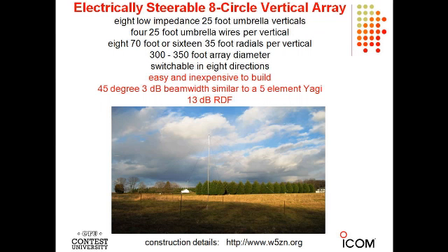At the base of this antenna, these low impedance antennas work best when they are tuned to resonance. They work well even if they're not tuned to resonance, but they work best when they are. And all that's in the little box, and you can learn the details at Joel's website, but all that's in the box is a little inductor, 28 microhenries. It's the size of your fingernail. Remember, these are receiving antennas. And the base feed impedance here, because the radial system is sparse, is about 20 ohms. Almost all of that is lost in the sparse radial system, just 8 radials.